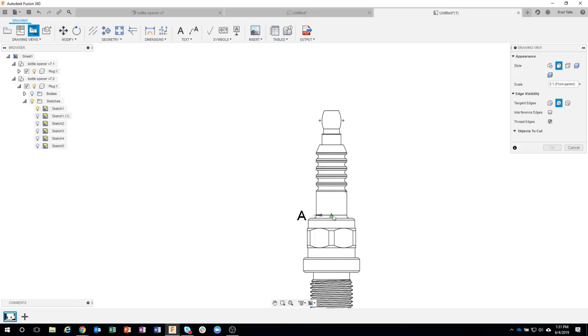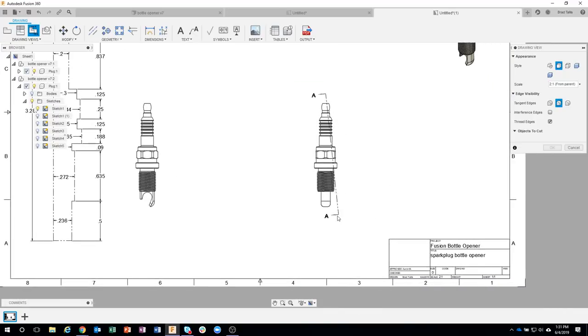You can see right here, we're projecting off of that guy. Okay? It's really cool. I can even grab radiuses. So this little point here is actually the center of that curved radius. So you don't really have to do a lot of projections and stuff. I'm going to just click up there, and then come down here, and you can see it automatically snaps to vertical.